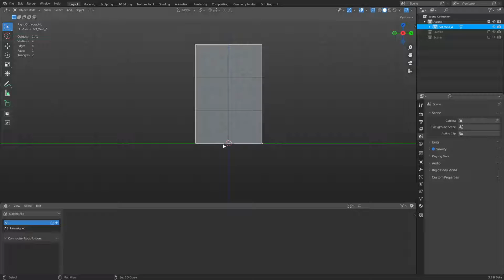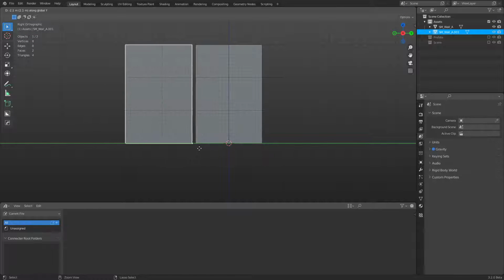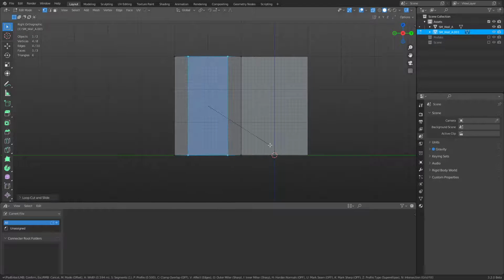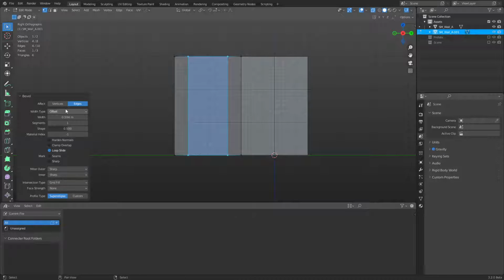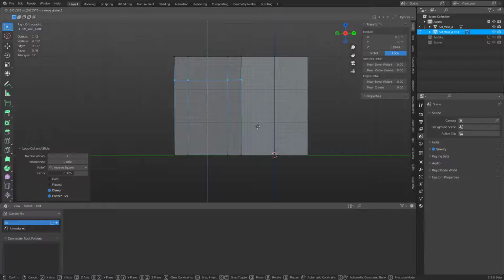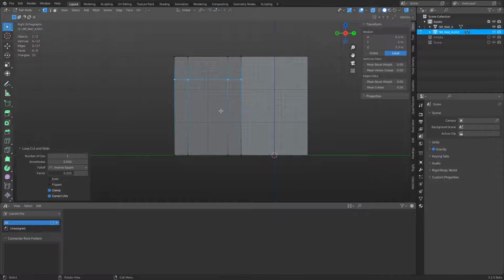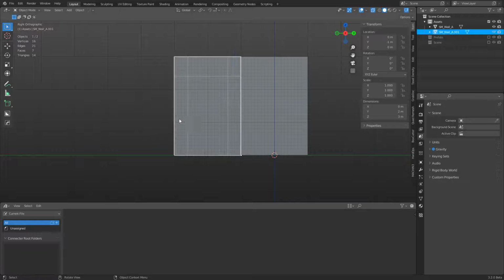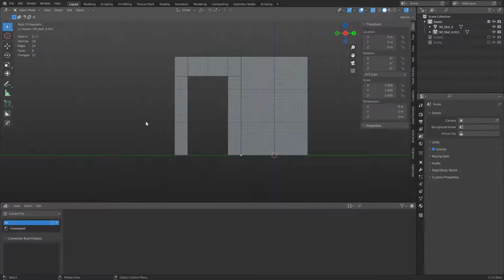This is okay. So I'm going to actually duplicate this wall. Go ahead and create a door frame area. Double this by width. I'm going to try to go through this as fast as possible when it comes to modeling because we got a lot of other stuff we got to take care of. Now, I am going to put a floor that's 10 centimeters thick. So in this case, if I want this to be a 2.3 meter tall cut here, I need to bump it up 10 more centimeters, right? Here we got everything snapping. Okay, there we go. So we got a wall unit now. No problem.